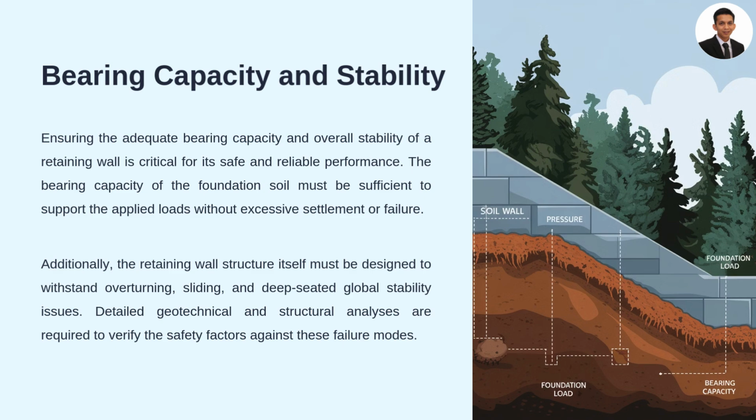Number 3. Global stability. This examines the stability of the entire slope, not just the wall. Deep-seated failures involving the soil mass beneath the wall are considered. Software like Plaxis or GeoStudio is often used to model these stability checks, incorporating real-world soil and load conditions.